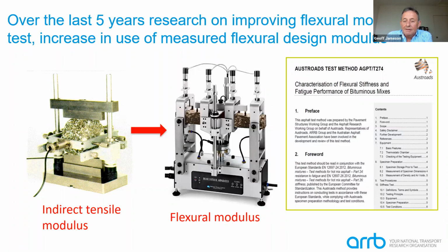So it's not behaving in an elastic manner at high temperatures. So that's the issue, that it's no longer an elastic material. And so there's just difficulties in actually estimating a valid fatigue life from the testing, and also a valid modulus value above 30 degrees.